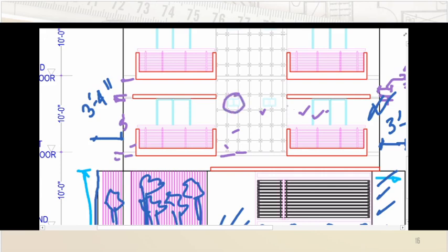What is this? This is a toilet window. As I discussed in the last class, all the windows, unless it is the stair window, will start from 7 feet above, and go below according to the dimension of the window. So if we use a toilet window of, say, 2 feet by 1 feet height, then it will start from the same level as all the doors and windows do, and then go below 1 feet as depth, and will take 2 feet as width.